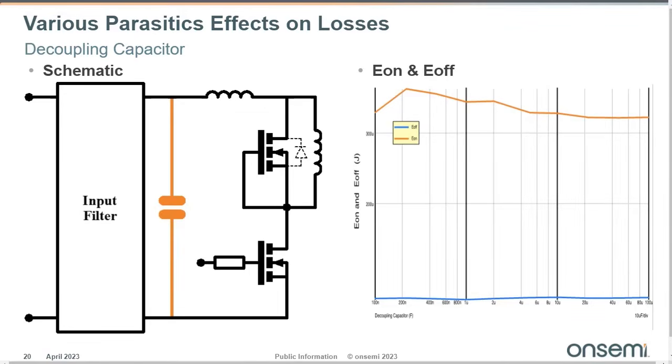Let's say I'm talking here about film capacitor and not chemical capacitor for high frequency, because they are not so good for high frequency. Here I'm talking of film capacitor for high frequency decoupling. You can see that 1, 2, or 4 microfarad is a good value, and 3 microfarad is a good compromise compared to the gain that you can obtain if you put 20 microfarad.